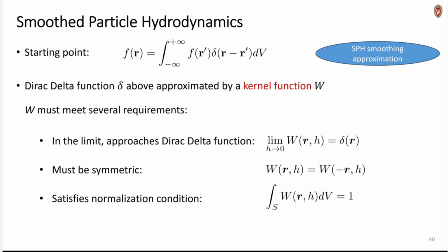I do not expect you to understand this unless you work in this area, but SPH is a way of semi-discretizing some time-dependent space PDEs, like the Navier-Stokes, for example, semi-discretizing in space, right? You can use different ways of replacing the spatial derivatives in such a PDE with algebraic expressions so that you end up with a time-dependent ODE.